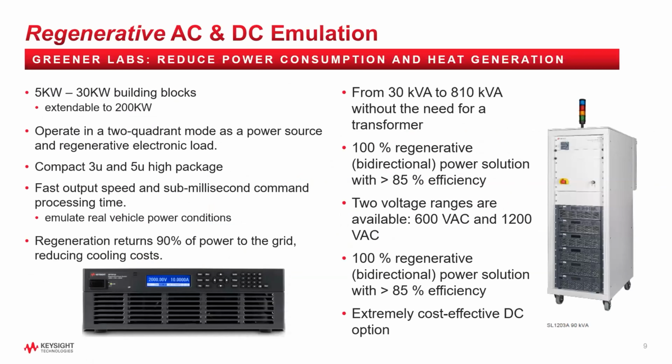So speaking of emulation of either the charging station or the EV, we have our regenerative power systems that we show here on the left side. We have 5 kilowatt to 30 kilowatt units that can be racked up and extendable to over 200 kilowatts. These operate in 2-quadrant mode as a power source or as a regenerative power load. So while we're going through a charging session and we're emulating an EV, for example, we use these as loads,